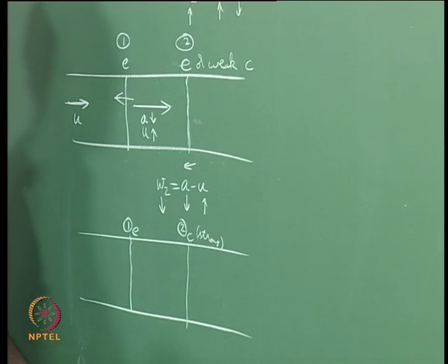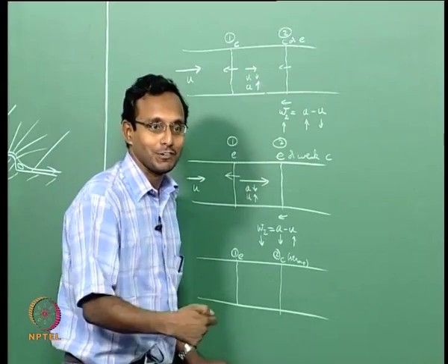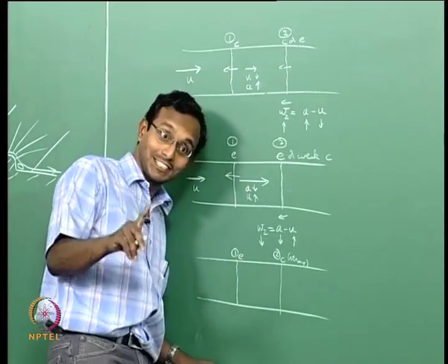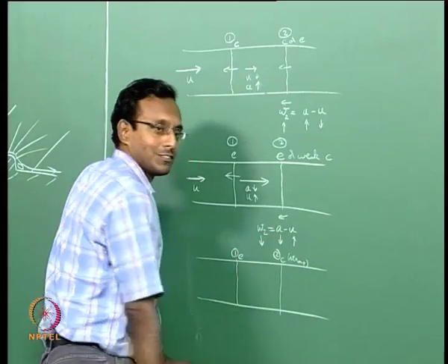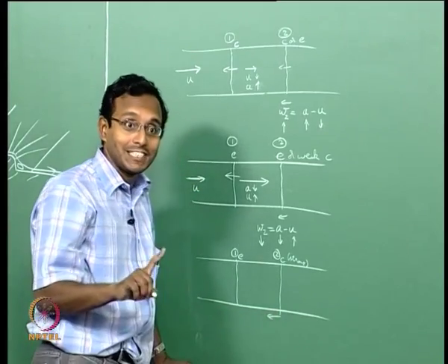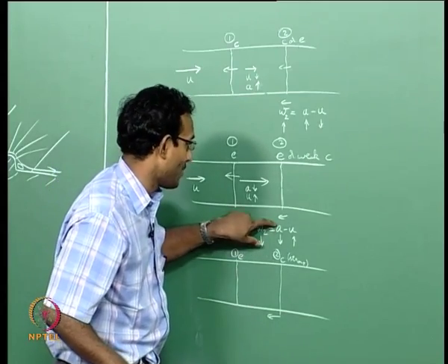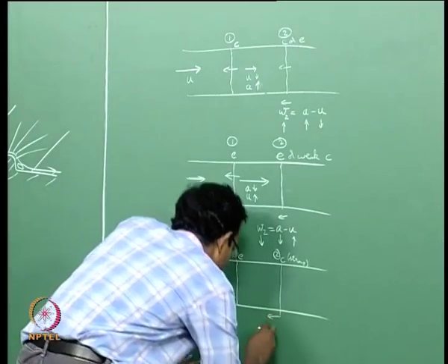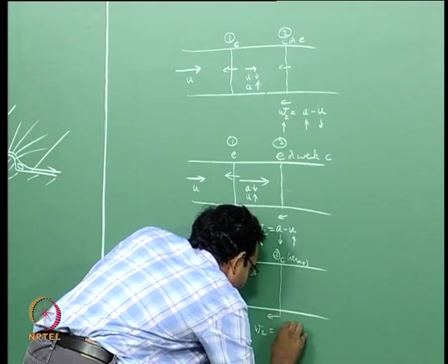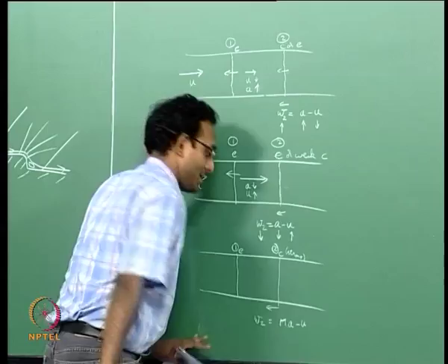then it will have a good speed, it will travel with a Mach number more than 1, right. It is like a shock can travel more than speed of sound. Okay. So, if that is the situation, then there is a possibility that this will cross this, okay. Then there is a possibility that this may reach it. I am still saying there is a possibility, it need not reach it. Maybe I just have to multiply this with say 1.1, okay. It will look something like this, right. W2 is equal to M of that wave multiplied by A minus u. This is what it will be finally.